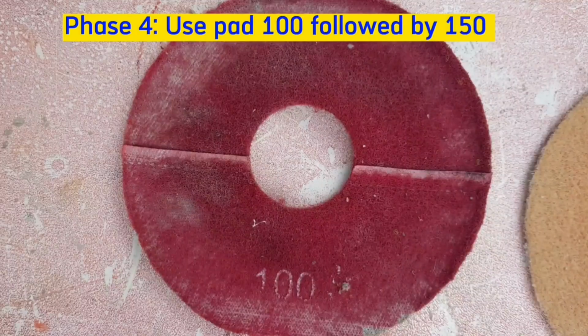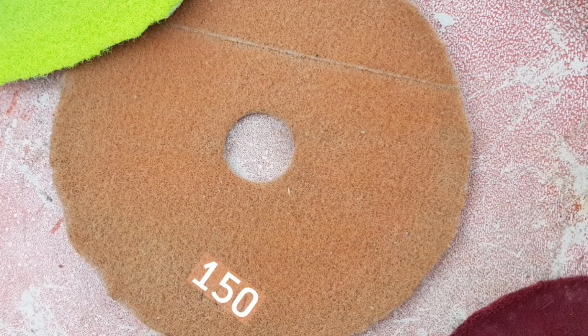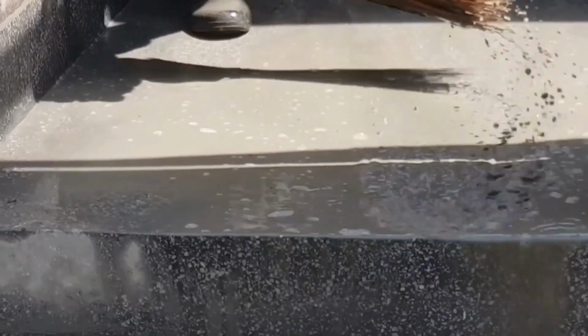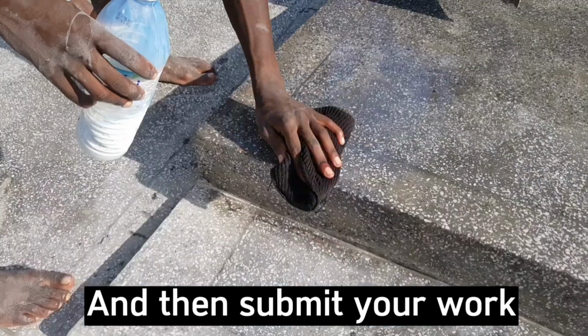The fourth phase is to run pad 100 followed by 150. At this fourth phase, if you are not considering something luxurious, you can wash with clean water and apply premium self-shine polish and then submit your work. The main purpose for this polish is to make the floor shine and also make it easy to clean.